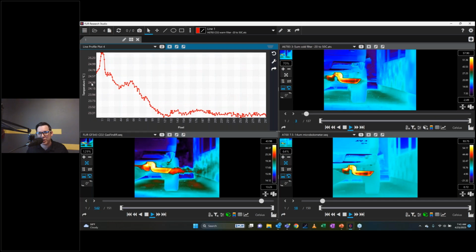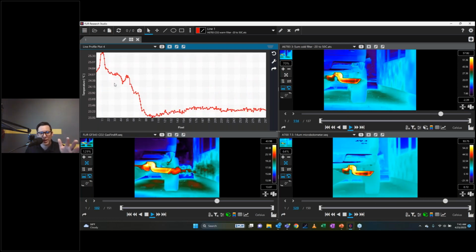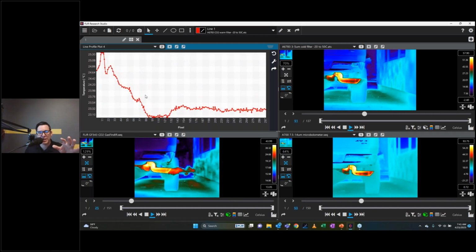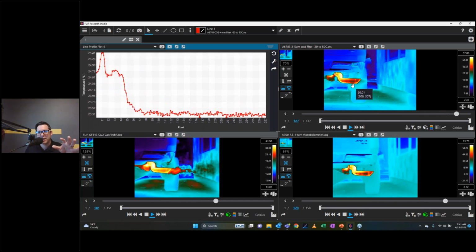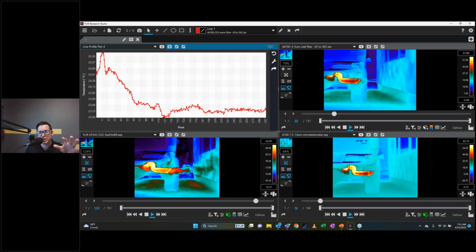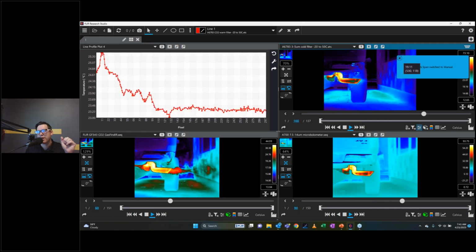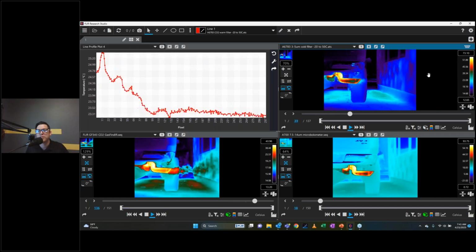Gas is not completely opaque, and therefore you can't read the surface temperature of it. There's a lot of things you can do to try to, but it's an extremely difficult problem. So this is all about imaging the gas, not really measuring it, but the apparent measurement will give us an idea of what's going on here. Again, this was that warm filtered option. On the right-hand side, this has no filtering, and you can actually still see some of that exhaust coming through. Remember how I showed you earlier the response of a 3 to 5 camera? It had that drop in transmission where CO2 is. That's what we're seeing here in this exhaust, because there is a lot of CO2.